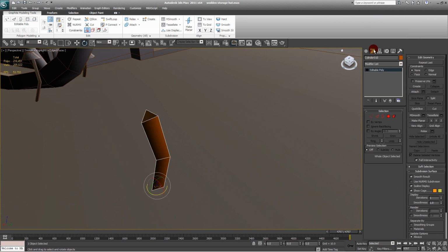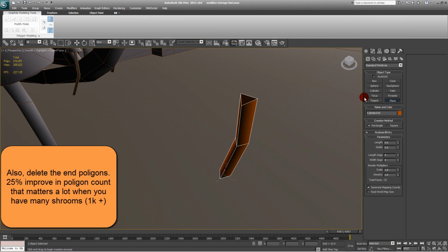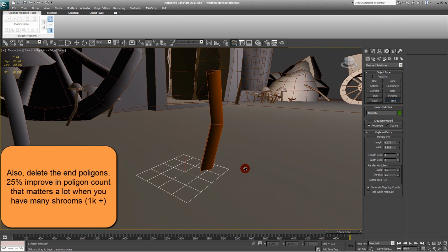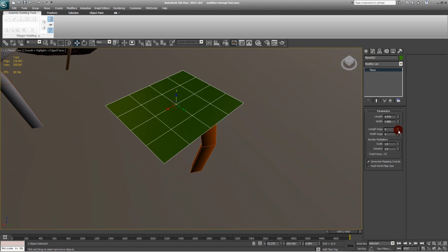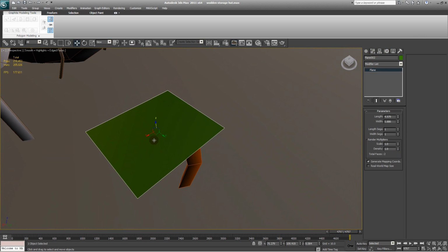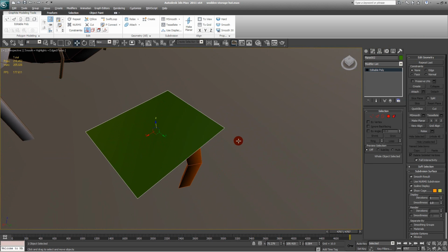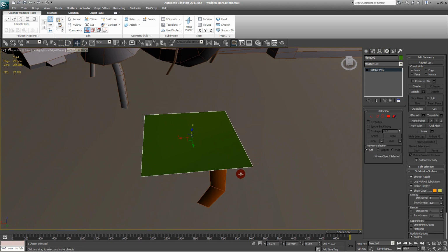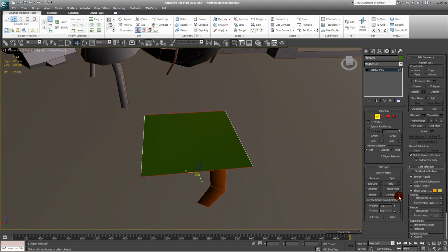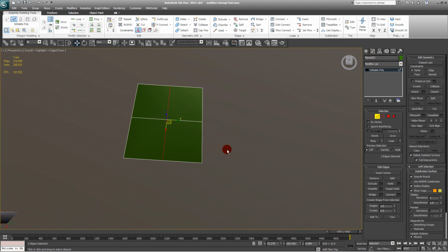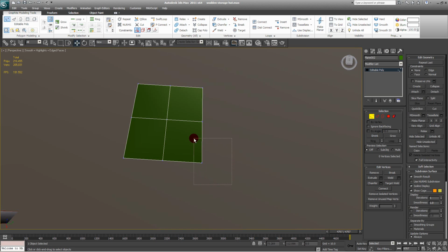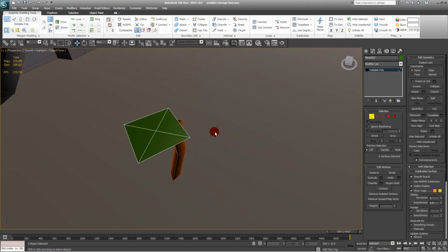And the last thing that we should do is just to make a cap for the mushroom, just to go and create a plane, following the principles that I've explained to you in the first tutorial. Just drag it up like that and go into modify, make sure it has got segments set to 1, and right click convert to editable poly. Then with this mode off, we would want to press 2 and connect those segments with 1 again, and following the optimization pattern in the first tutorial, we will just go into the vertex mode, select the sides vertices, and create a rhombus by backspacing those vertices.